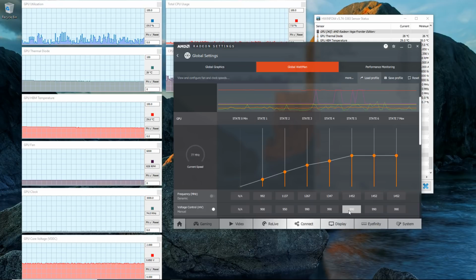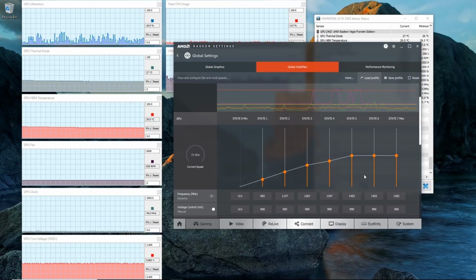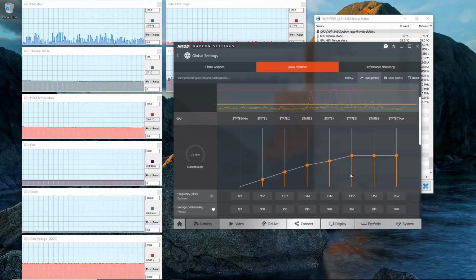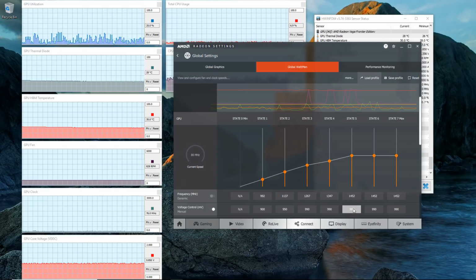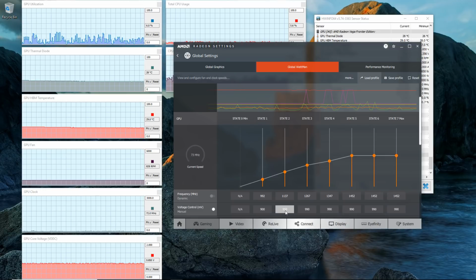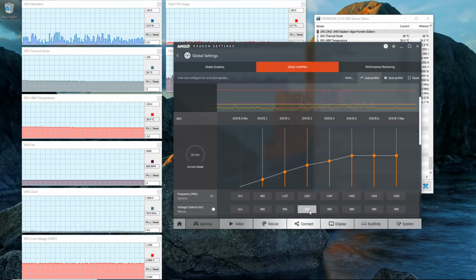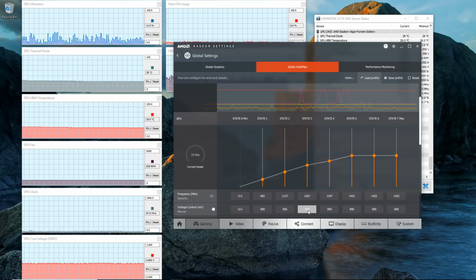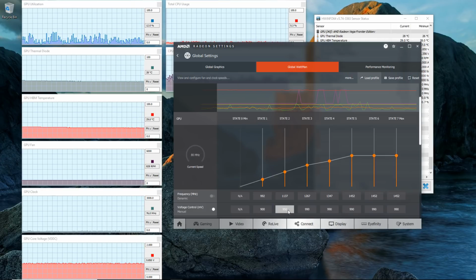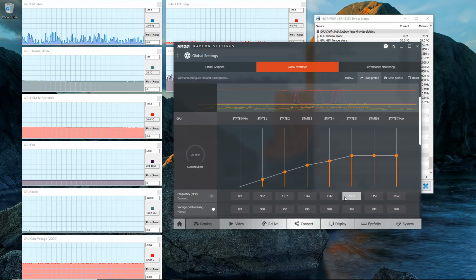So what I did in my case, because I have the ability to adjust all of the states, once I found out that I could handle 990 millivolts at this 1452 frequency, I just propagated that backwards until the next value was lower. So this one I think was like 1 volt at one point in time. So I just went back and this value was lower, so I just left it alone.